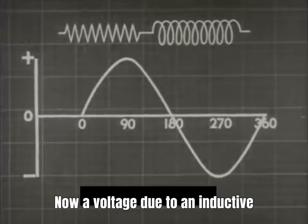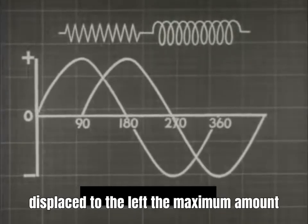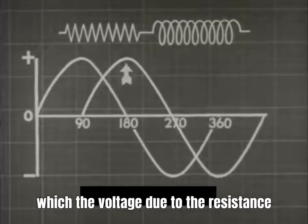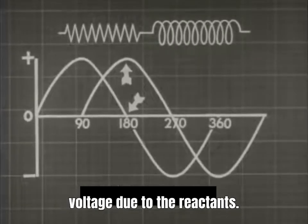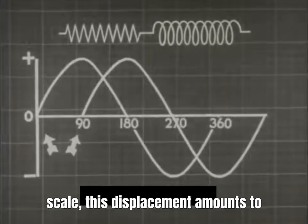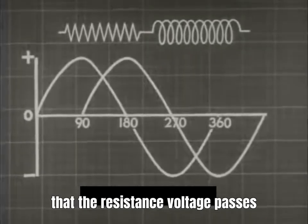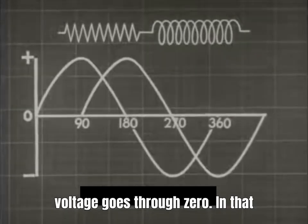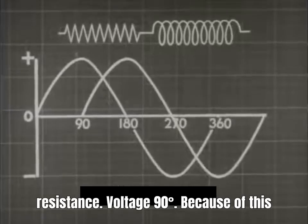Now a voltage due to an inductive reactance in series with the resistance is introduced. You will expect it to be displaced to the left the maximum amount, due to the reactance, or to the point at which the voltage due to the resistance alone is maximum at the time when the voltage due to the reactance is 0. As can be measured on the scale, this displacement amounts to exactly 90 degrees. Or you can say that the resistance voltage passes through 0 90 degrees after the inductance voltage goes through 0. In that respect, the inductive voltage leads the resistance voltage 90 degrees.